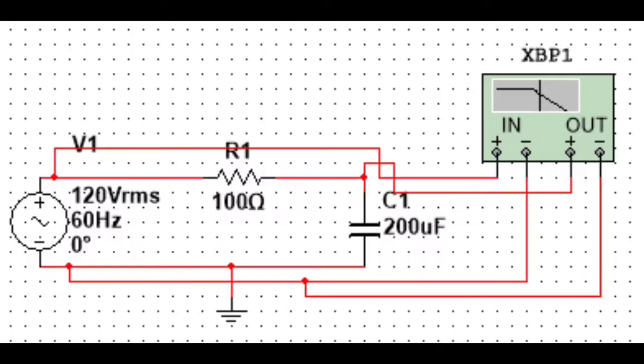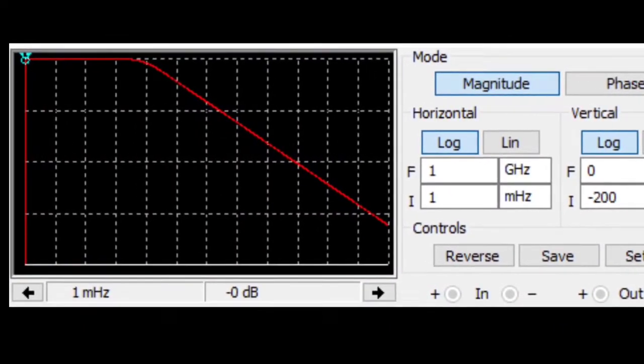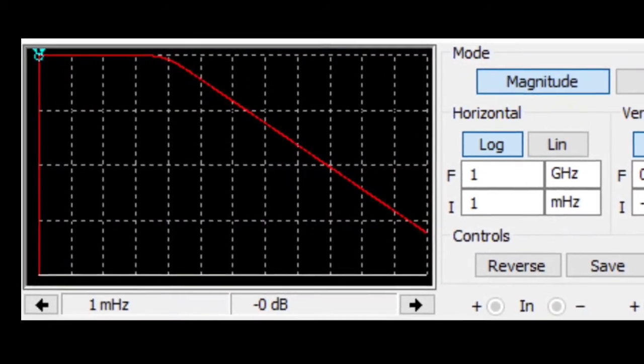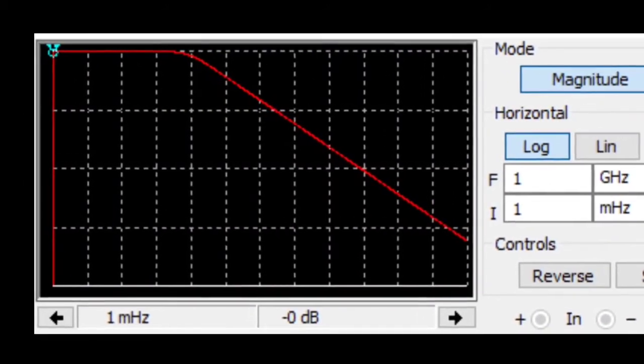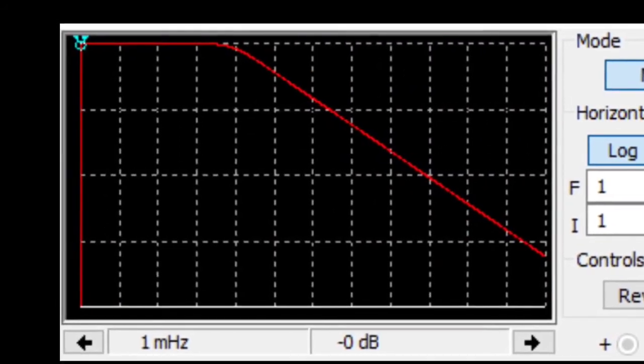A simple passive RC low-pass filter, or LPF, can be easily made by connecting together in a series a single resistor with a single capacitor, just like in our experiment. The bode plot shows the frequency response of the filter to be nearly flat for low frequencies, and all of the input signal is passed directly to the output, resulting in a gain of nearly 1, called unity.